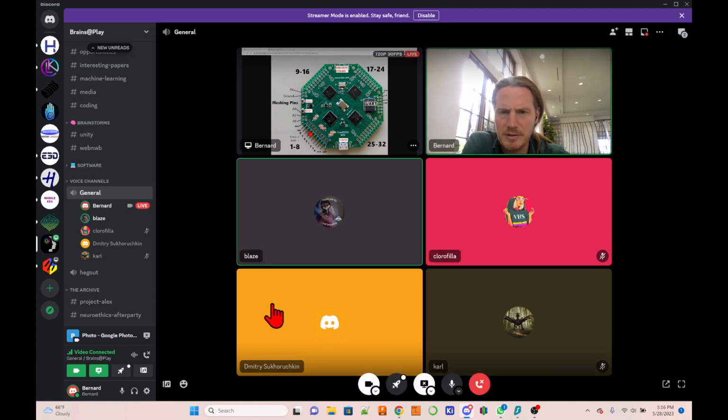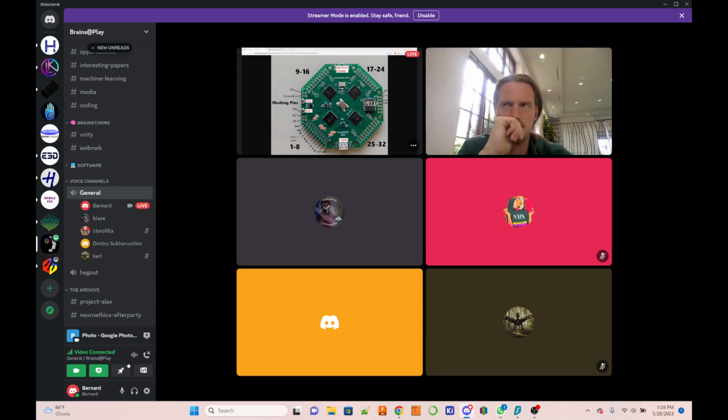For every channel, the inside pin is negative and the outside pin is positive, right? But that's flipped on the Cyton, except when you're using SRB1, where you plug your signal into the negative, for reasons I don't fully understand. I presume it's just the way the amp's designed.